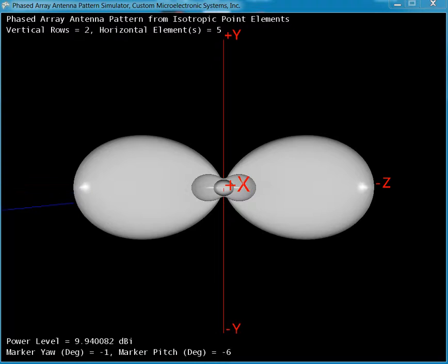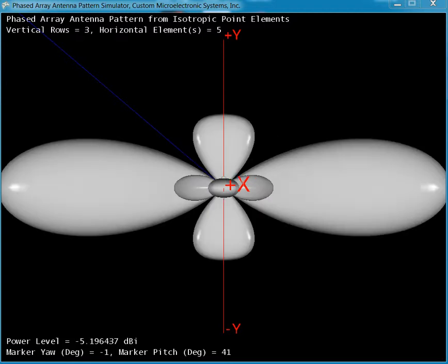and so if we sweep to 7 dBi for the 3 dB down point, roughly 42 degrees on one side and 42 on the other. So we're seeing the similar performance as adding point sources horizontally. As you add them vertically, we're now 2 rows vertically, so our beam width is roughly 82 degrees. Going to add a 3rd row.